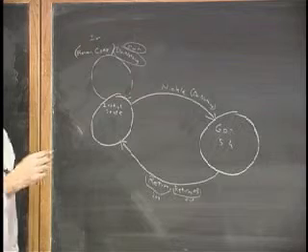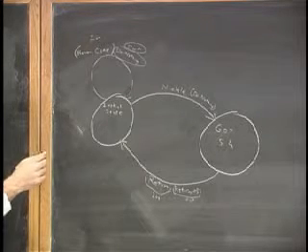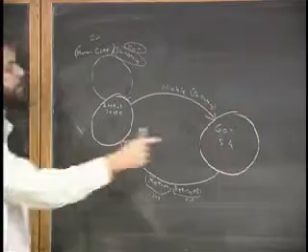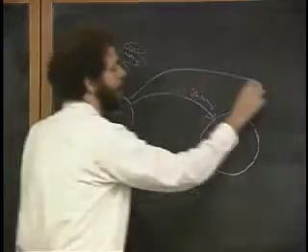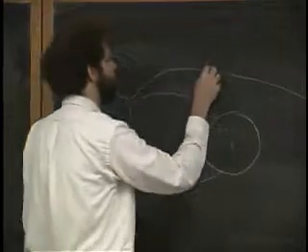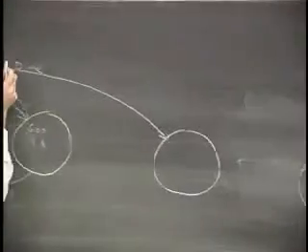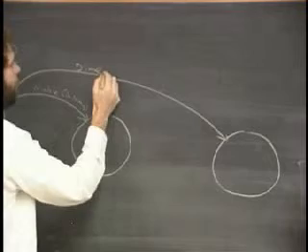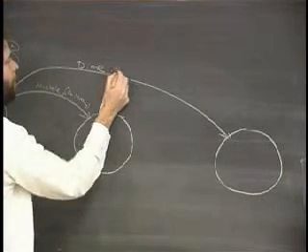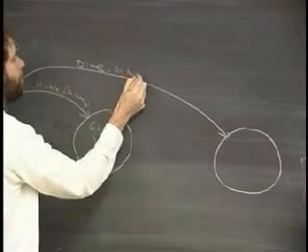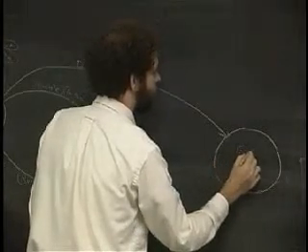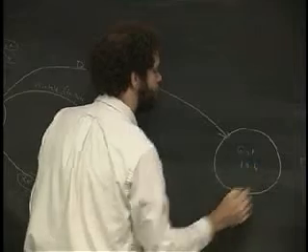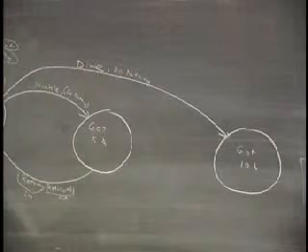We clearly want to remember that, but we don't want to remember it in this state, so we need another state. So if they input a dime, like here, that was one of my inputs, right? Dime. We want to, again, do nothing as an output. But we want to remember it differently, and we put it in this state saying got 10 cents. Good. I think that we've handled all 4 possible button presses that could happen going from this state.